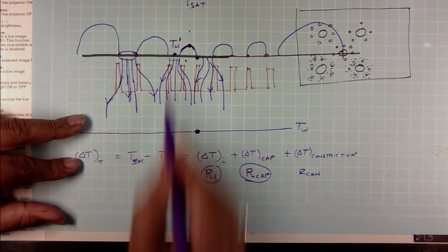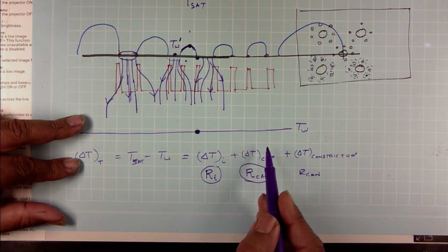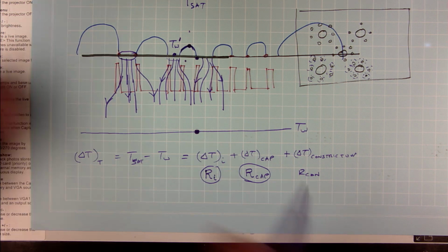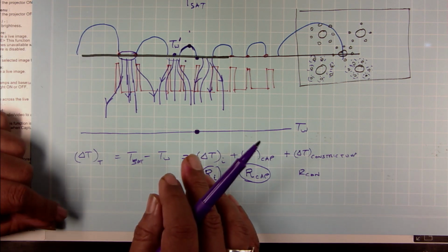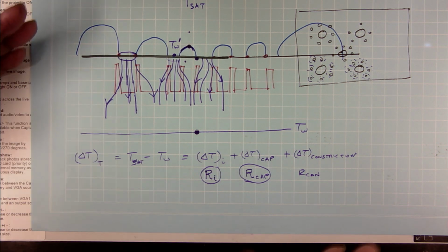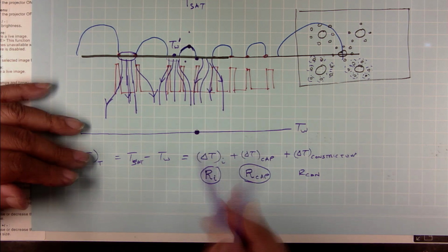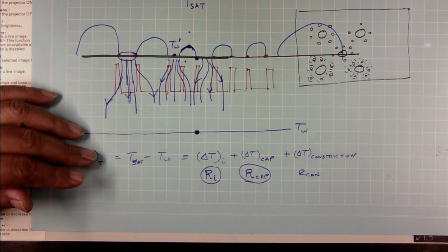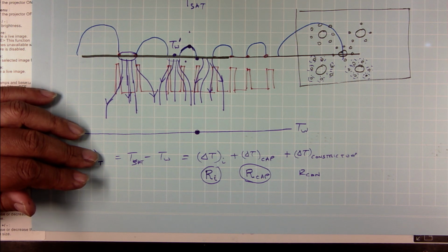So if the heat flux lines were uniform, then it is very simple. It is whatever is this thickness divided by K. That would have been my nominal resistance, but because the heat flux lines are constricted and expanding, your actual resistance is going to be higher than the pure conduction resistance, because of the non uniformity in your heat flux lines and the temperature lines, because it is not a uniform linear drop in the temperature.